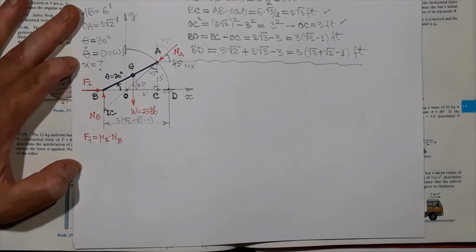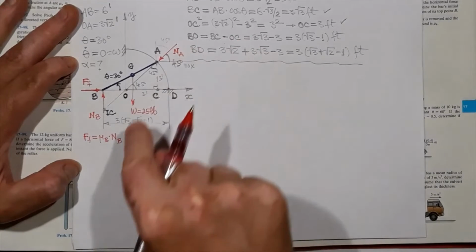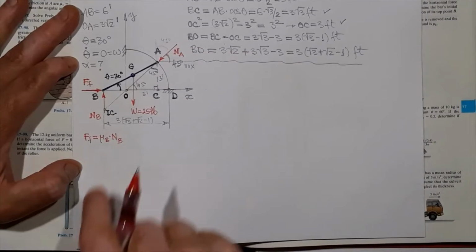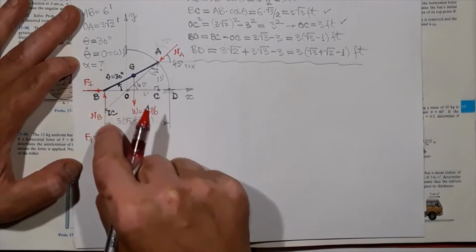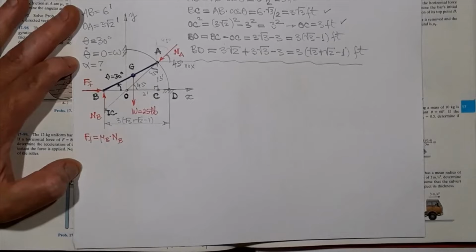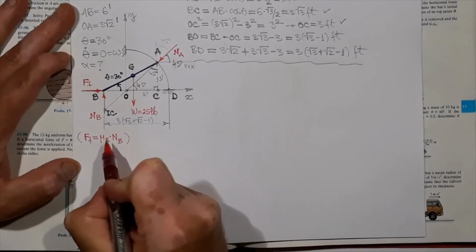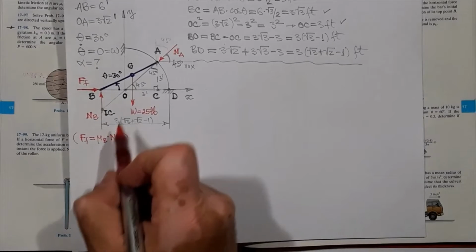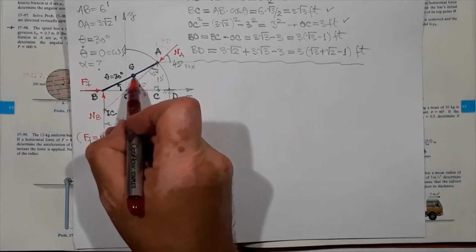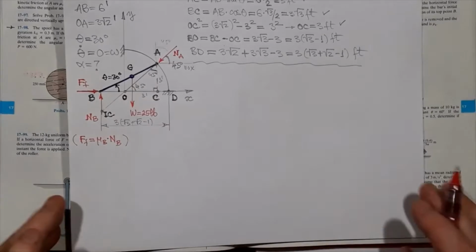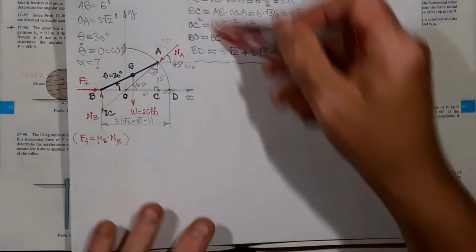So we have 4 unknowns. There's the normal force at A. There is normal force at B, I said 4. And then friction force, we stated it's normal at B times friction coefficient. We're going to see the acceleration of the center of mass over X and Y occurring. So we need to use, in addition to geometry, some